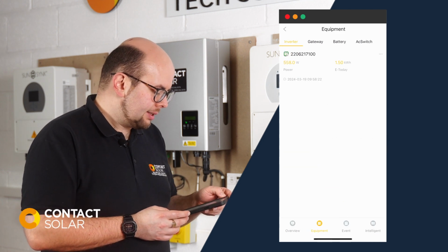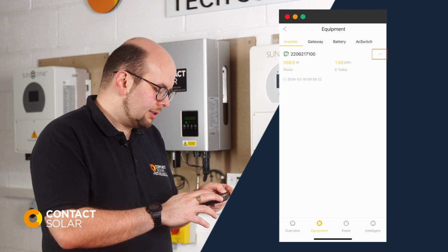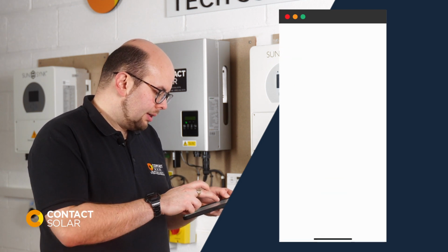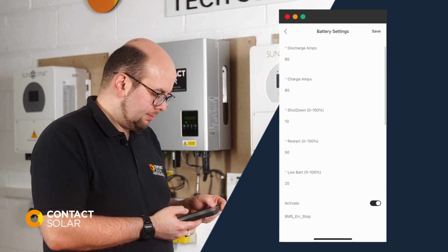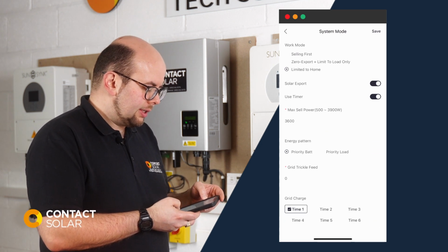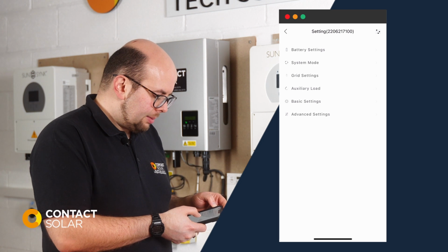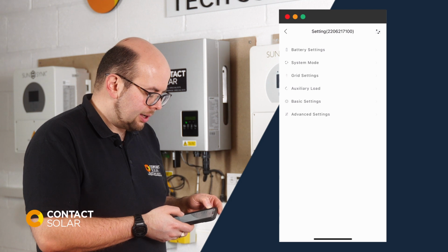To access the settings for the inverter, tap on the three dots to the right hand side of the inverter's serial number. Select Settings. The battery settings are configured at the point of installation. The system mode settings can be used to adjust grid charge timing and target state of charge. Grid settings, auxiliary load, basic settings and advanced settings are all set up during the installation process.